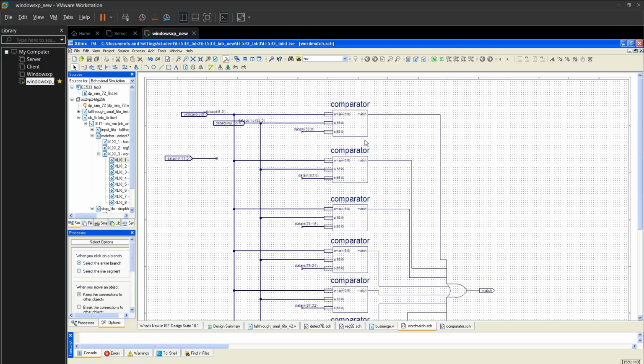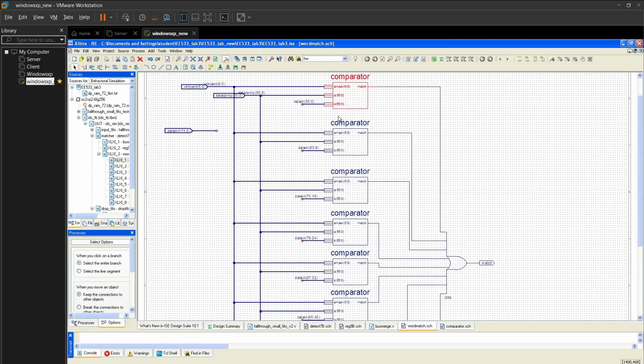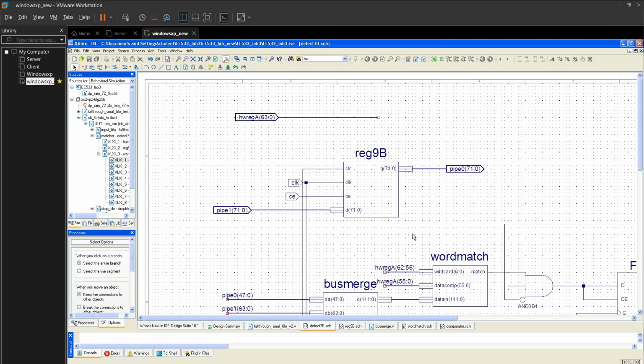These comparison blocks are 7 bytes each. They check whether any of the 7 bytes match the malicious data pattern's 7 bytes. The wildcard is stored in the same hardware register as bits 62 to 56. Our hardware register is around 8 bytes, of which we keep the last 7 bytes for checking the 7 bytes. So this is the design for it.